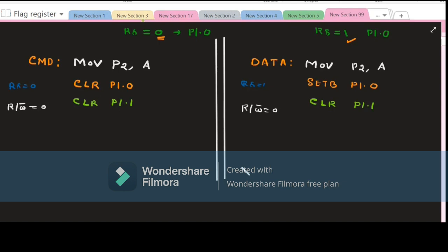That's it. Now after that simple line, we have to enable and then disable. So for the enable pin, first of all you have to set the bit port number 1, bit number 2, and then you have to clear. Here also you have to set the bit, that means port number 1.2, and then clear, that means port number 1.2 to zero. That's it.